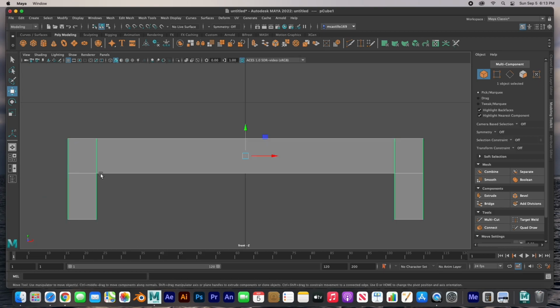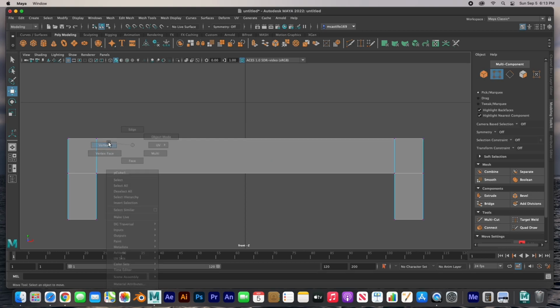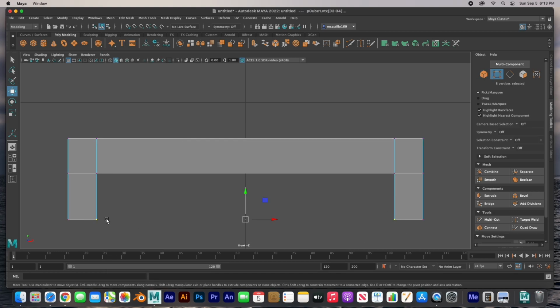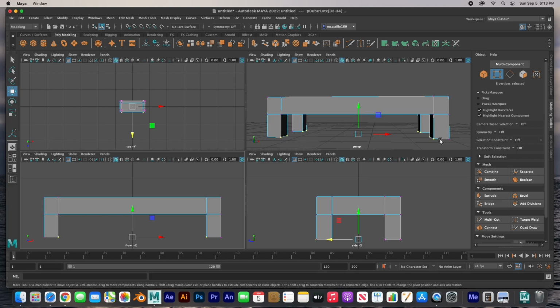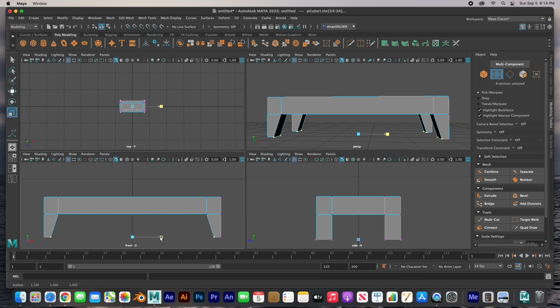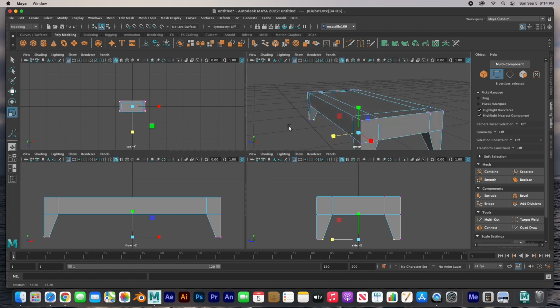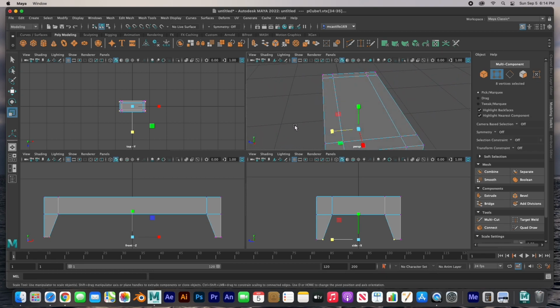I want those tapered fancy legs that are on the couch, not these bulky legs. And so I'm going to go to vertex mode and I'm going to select all 4 of these. And you only see 2, but it's actually 8. There they are. 4 on each side. That's 8. You can see that if I click here, I select all those 4. And then these 4, 8. And I am going to do that same trick and I am going to scale. Hit R to scale. And then just size them in like this. Right about there. And do the same thing on the side view. And then scale them out. Before you know it, they start looking like cool legs. Check that out. One more thing, the back.